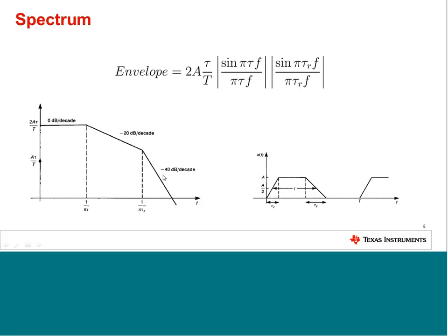So critical frequencies we have regarding EMI and noise are the switching frequency, of course, because this is how the converter operates, but as well, in addition to that, the slopes at the switching transition of the current waveforms and of the voltage waveforms. So that's the theoretical part, which you just need to keep in mind for the application examples, or for the experiments I'm showing you in the following slides.